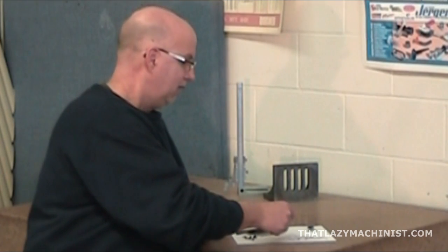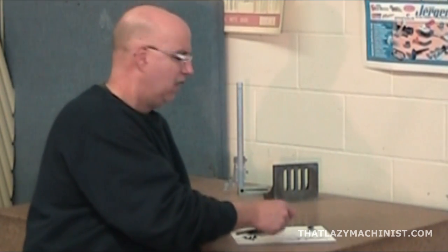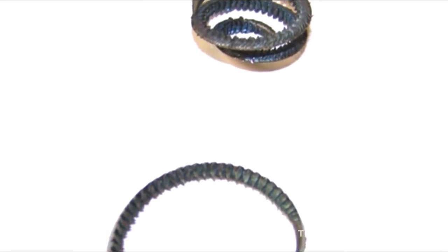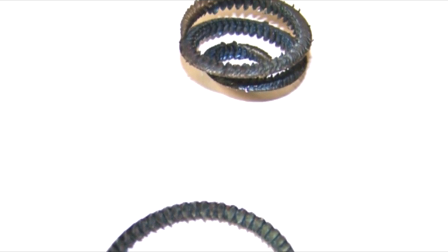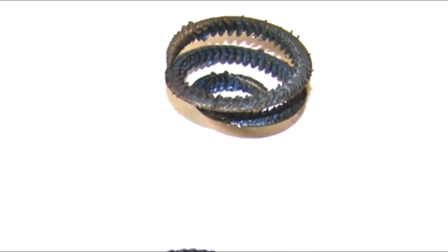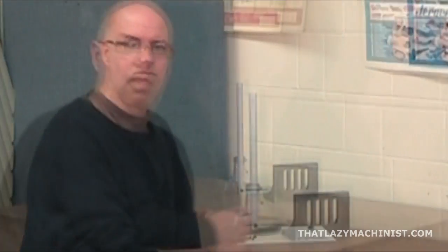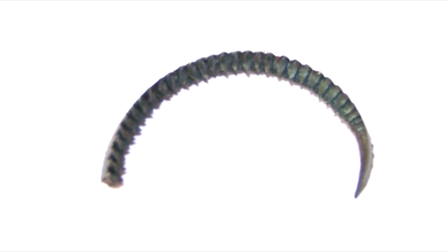As we can see, these discontinuous chips are torn off more than formed, and they are the result of an excessive depth of cut and/or an excessive amount of feed. These chips are to be avoided, since they are the result of an excessive amount of cutting force. They have a tendency to deform the part that we're machining and produce a very poor surface finish.